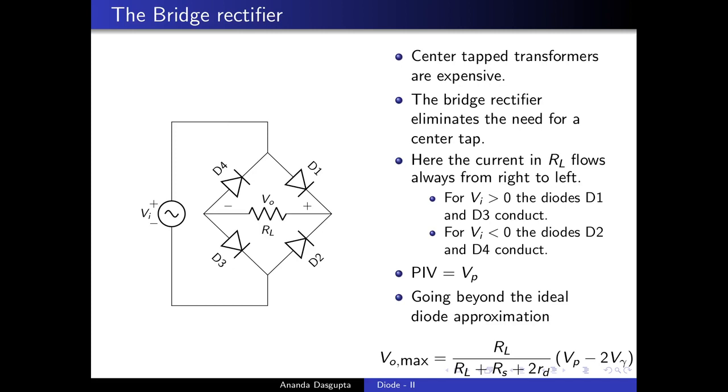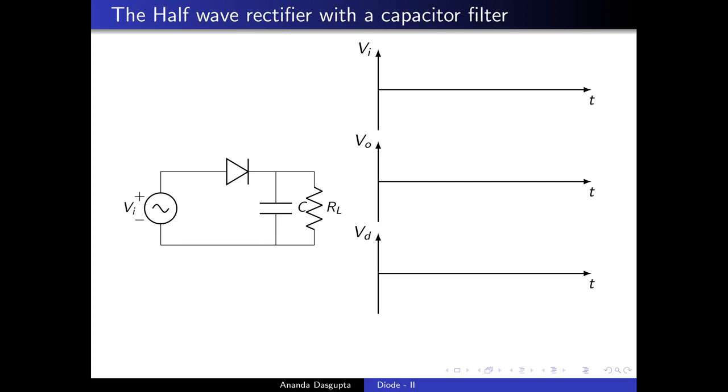And one very simple modification, which I am going to explain qualitatively in this last section of the video today, is something which is called a capacitor filter put on a rectifier. So the circuit essentially is the circuit here, which is exactly the same as the half-wave rectifier circuit that we had described before. There's just a capacitor added across the resistance. Now, truthfully speaking, we can easily understand why addition of the capacitor should make the output better in terms of what we want.